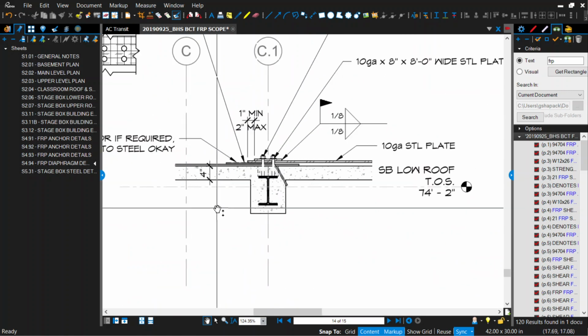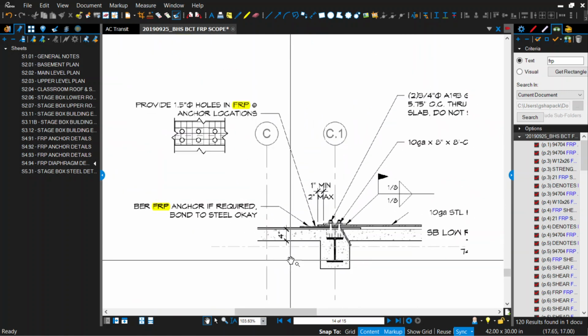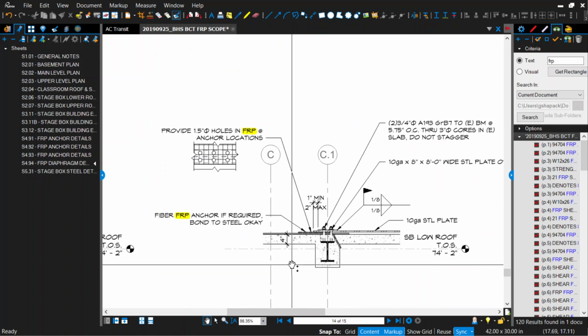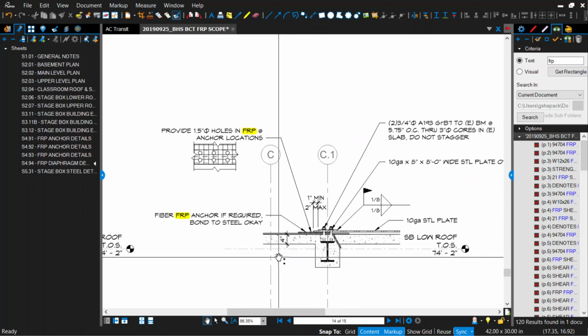The way that was drawn before was something like this, and it looks like they've drawn it a little differently now. If we do our normal shear transfer detail, we basically have our L-shaped FRP with the 2-inch base radius, but after all the reductions we can only get somewhere around 5 kips per foot, and they need 37, so it obviously doesn't work. So what I told Annika is we'd have to do mortar ramps wherever we need the FRP, and have the FRP go like that.